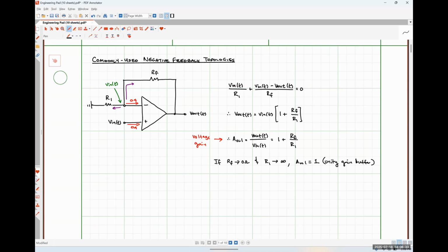So things like piezoelectric sensors for measuring mechanical deformation in prostheses would be something where you would use a unity gain buffer to effectively boost the power of the input signal by replicating its voltage, but allowing current to come in through the power supply terminals of the op amp itself.